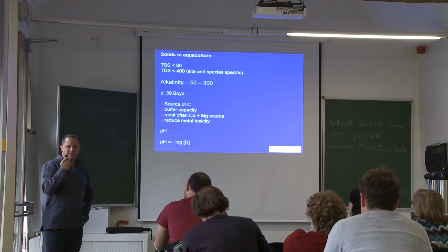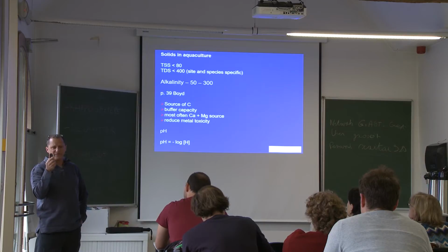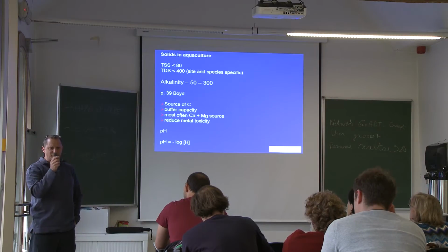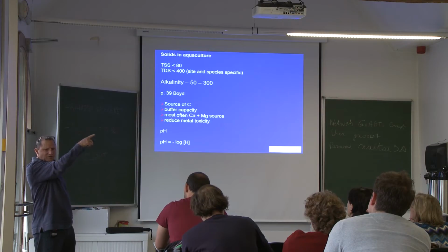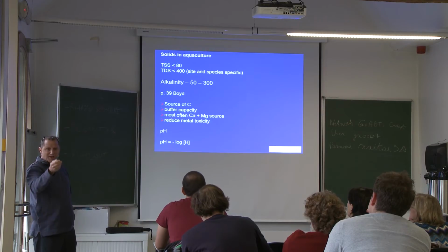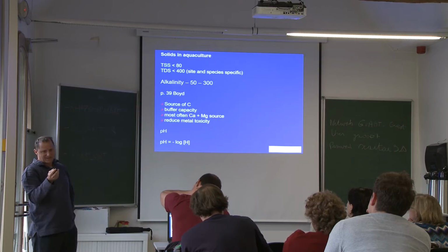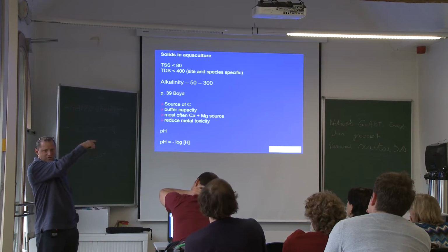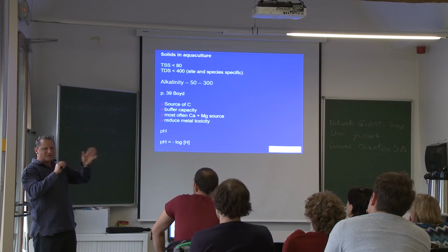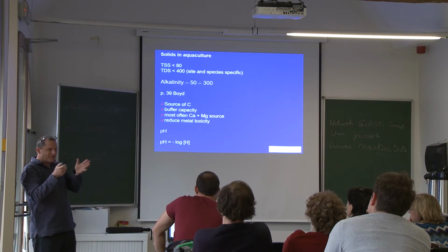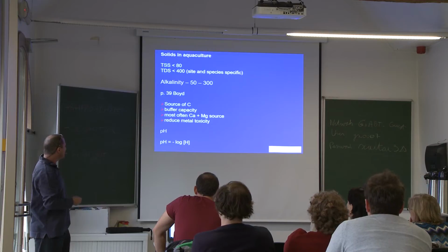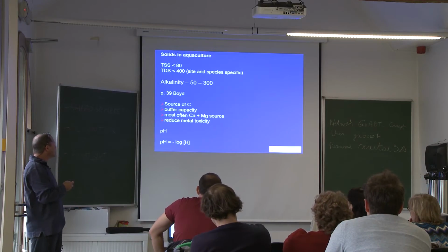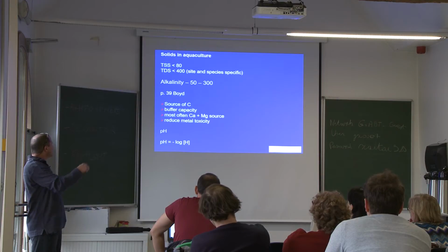In Australia, for example, it will be called NFR, non-filtrable residues, so it depends where you are, because sometimes in aquaculture this is also total soluble salts, and in plant studies I read that it's total soluble sugars. So just make sure we know what we're talking about, but here it's total suspended solids, and that's the term known in wastewater treatment and aquaculture as well.